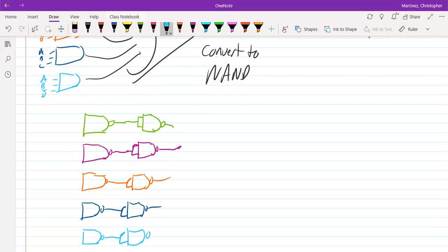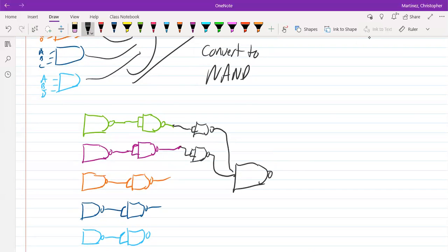All right. Then we had this OR gate in black. I don't want to draw this far away, so let's do it here. We had this OR gate. Okay, how am I going to do the OR gate? I got to make it as a NAND gate. And this had NOTs on the inputs. And those NOTs get tied to each color of the AND gate.